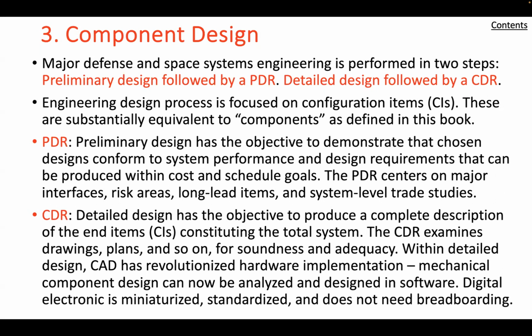Now let's talk about the critical design review. General procedures for the critical design review of the products of detailed design are similar to those for the PDR. The CDR is usually more extensive and may be conducted separately for hardware and software configuration items. The CDR examines drawings, schematics, data flow diagrams, test and logistics supply plans, and so on, to ensure their soundness and adequacy.